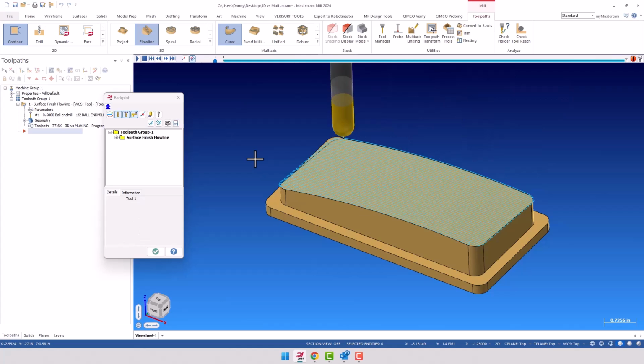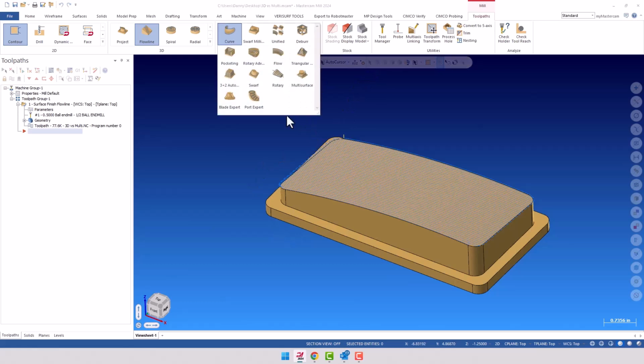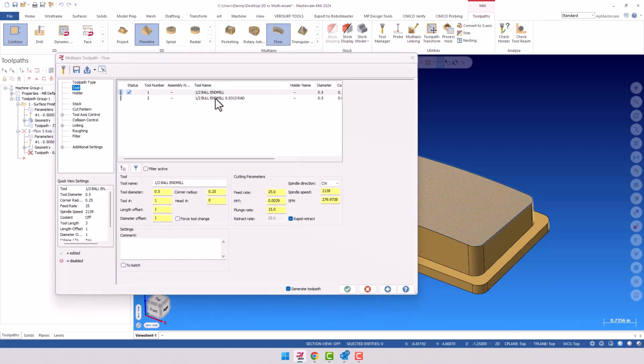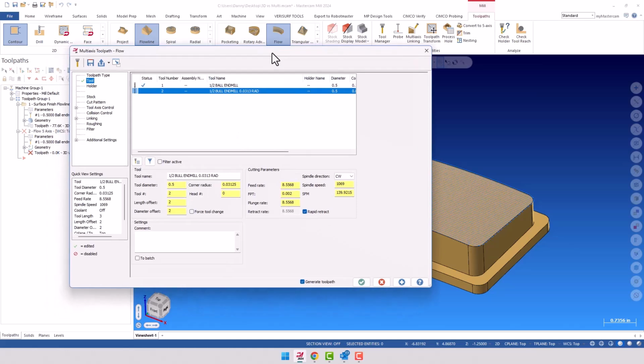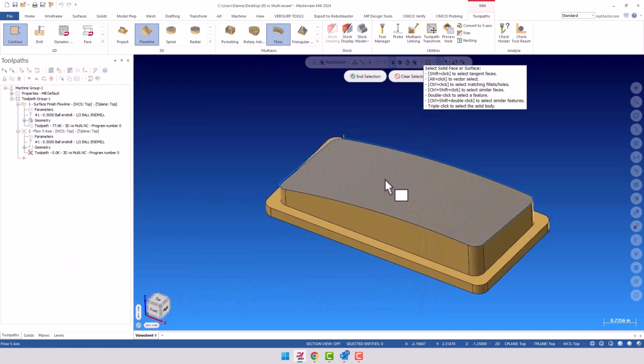Okay. But if you have a 5-axis machine, and let's say you want to work on cycle time, you've done good time cutting around the part with the contours. Well, you can use the same tool. Let's go over to the multi-axis panel, and we're going to use Flowline. Where is he hidden on me? There he is, right there. Flowline, and I'm going to pick a bull nose end mill this time, and I'm going to select my cut pattern. Same surface.